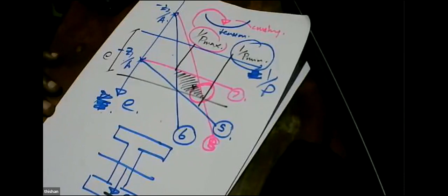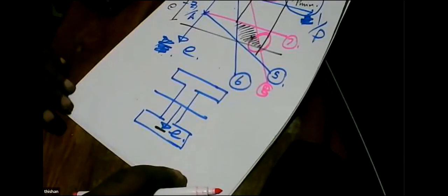Yeah. It's clear, right? So always select a pre-stress as low as possible, then you will get a very good situation, because you are not going to waste any money unnecessarily. And you should know, concrete is a natural aggregate-based material, and the only factory manufactured material we use is cement, and we can use fly ash, which is a byproduct. So basically, we are getting a high strength by using admixtures and reducing the water content.